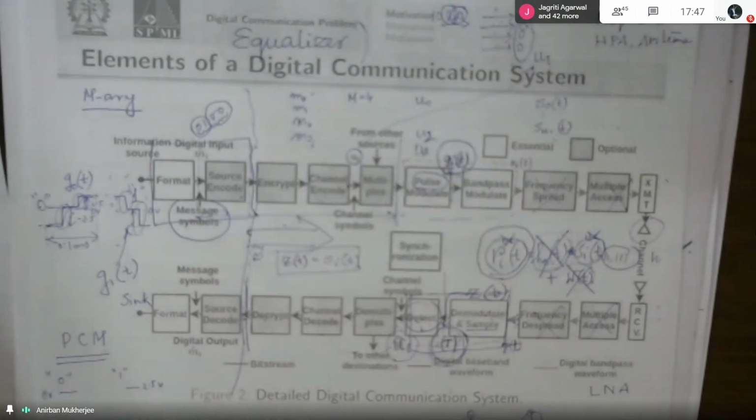So what will happen? I will remove those things which I cannot see, because it is useless to send it to the other side, since the viewer cannot see that information. That is unwanted information. That means source coding produces analog to digital conversion for analog sources. If it is a digital source, fine, and it removes certain redundant information, meaning what we can't see. A typical digital communication system would either use the source coding option, both digitizing and compressing the source information, or it would use simple formatting transformation, that means digitizing alone. So sometimes they don't do the compression.